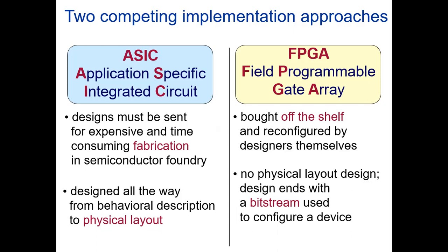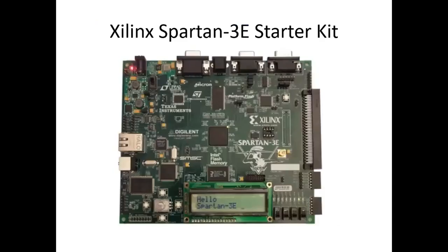In case of the FPGA, this is the virtual field I already mentioned in the previous class also. Virtual field means they have some logic present. We just configure it. So that's the reason I am writing here no physical layout design. The design ends with the bit stream used to configure a device.